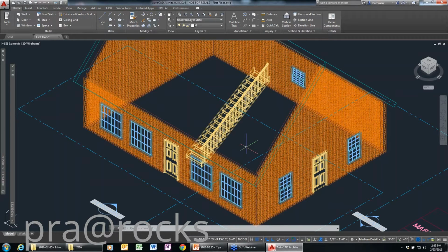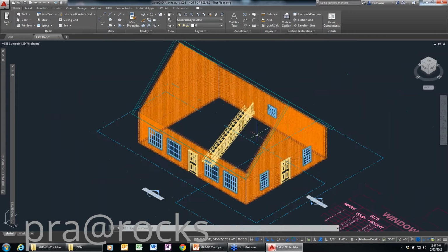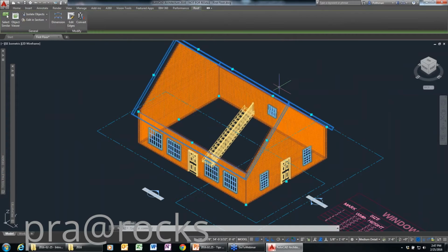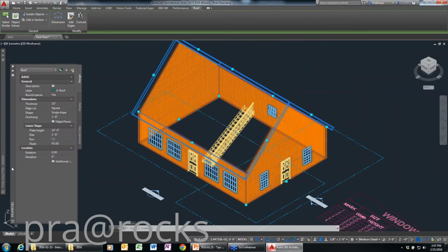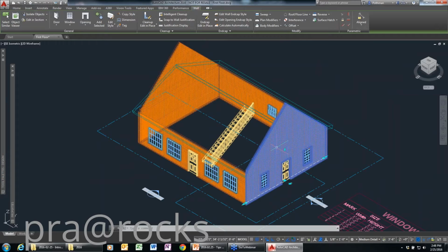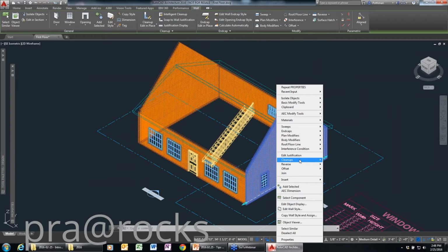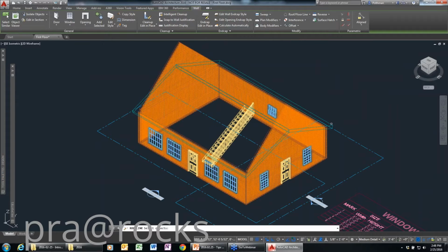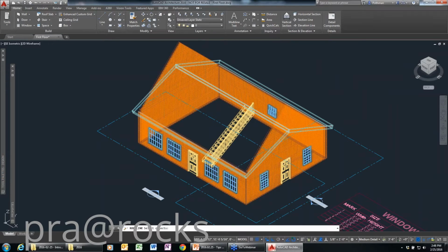Okay. And the other change, I'd like to have more usable room on the second floor. And I was thinking if you could change the roof to a 5-pitch roof, I think that would work better. Okay. Actually, right now I think I have a 12-pitch, which is kind of crazy. But let's change this to a 5/12 roof. And then I'm just going to go back to my walls, to roof floor line, modify the roof line. We'll do an auto project to fix my wall. Let's do the same thing over here.